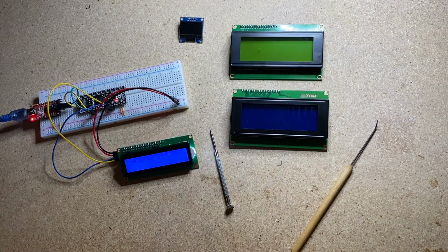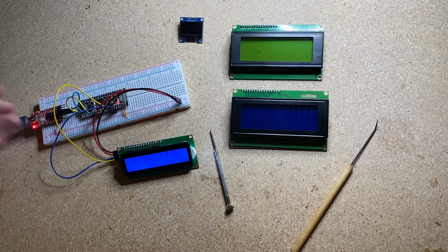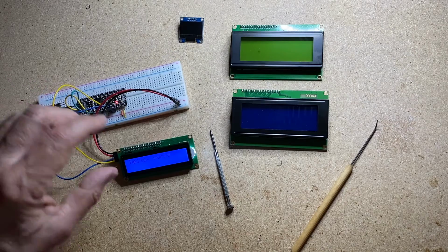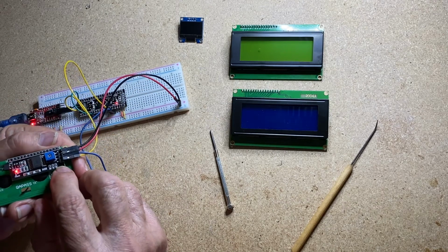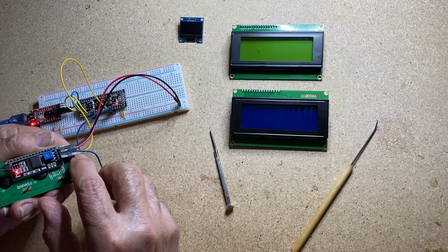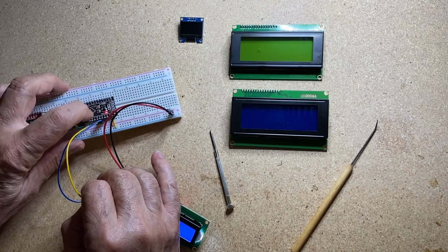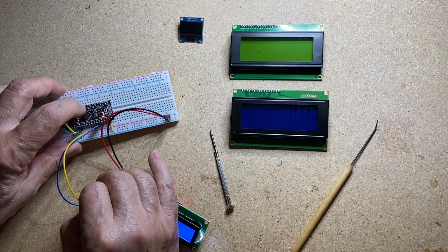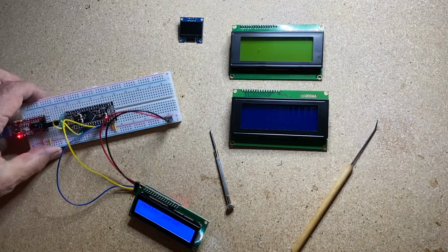The other thing is that when you use the STM32, you have to load the code. I use a USB to serial adapter, which is completely explained in some of my other videos if you have any problems with it. The I2C SCL and SDA, the yellow wire is on the SCL and the blue is on the SDA, are connected to SCL, which is B6 on the STM32, and the SDA is B7. That's I2C1. The STM32 has several I2C interfaces, but not all of them do exactly what you think they're going to do. So I2C1 using B6 and B7 are the ones you should use.